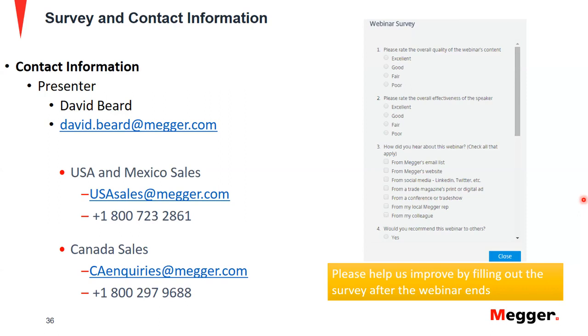But there is a way you can do that with our software. There is a feature called phase compensation on our screens. Let's say you're testing phase A. It would provide current values on phase B and phase C such that the zero sequence current turns out to be 0. So you can increase a phase value, but in a similar way keep the zero sequence current at 0. So your 51G would never pick up, but you can test your 51P. That's how you do the testing using symmetrical component theory.